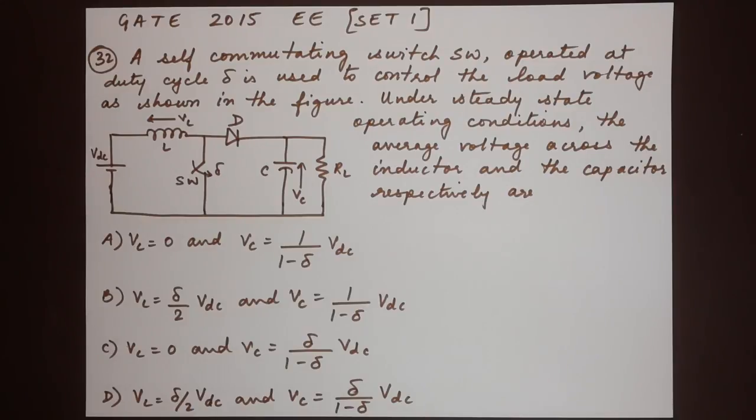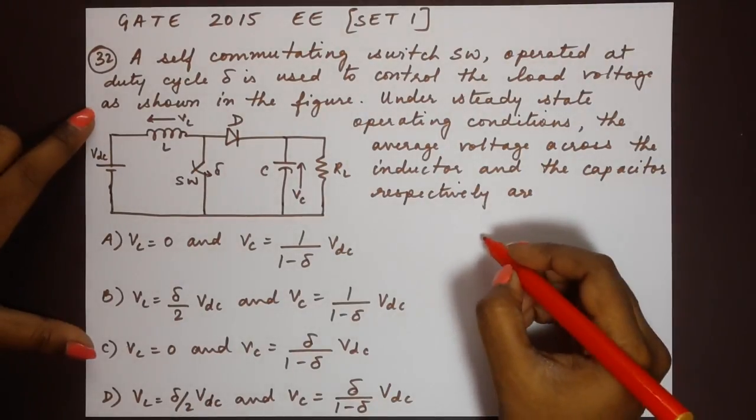Now they have asked us to find out the expression for the inductor voltage and the capacitor voltage. Now observe the figure given. You should know that this figure resembles the circuit for a basic chopper. More precisely, it resembles the circuit for a step-up chopper.